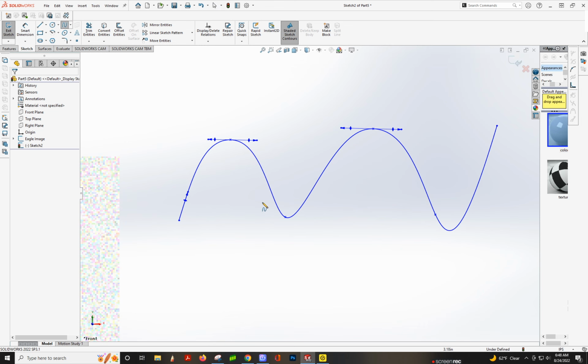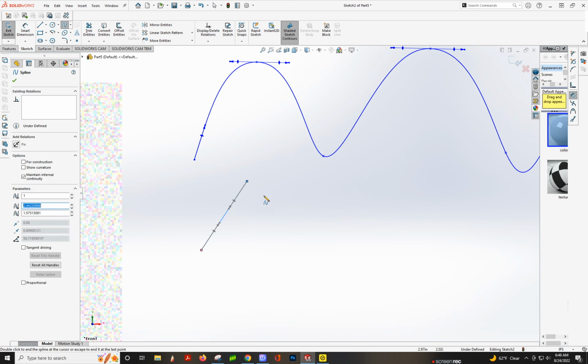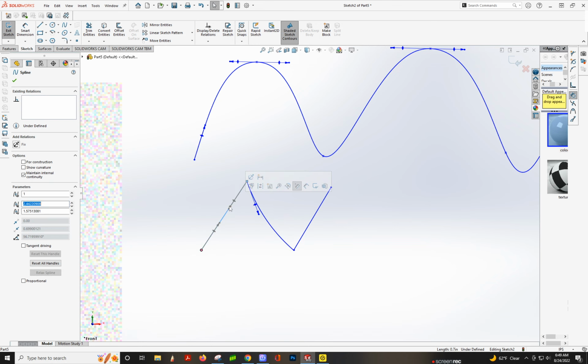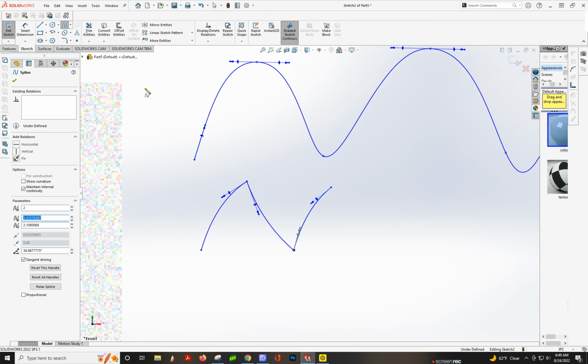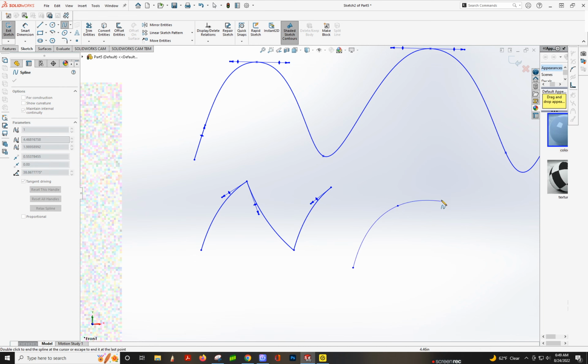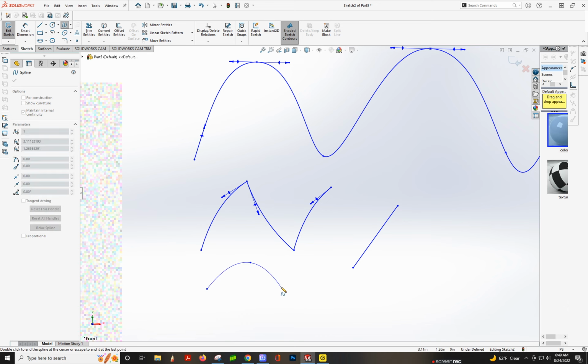So if you need to do sharp corners but curves with splines, what you do is you click and then you double click really quick. Click, double click, click, double click, and then escape. And then you can adjust the handles. Okay, so if you forget to double click, like I do because I didn't learn the double click thing until watching Solid Professor again yesterday, so almost 20 years of doing this the wrong way, then you just click, click, and then escape.